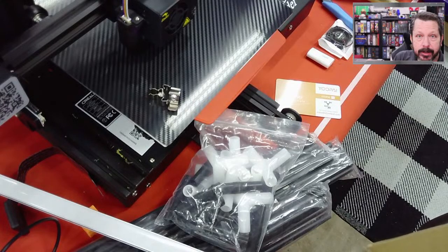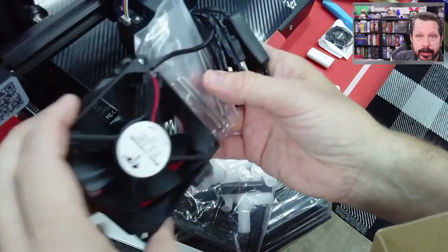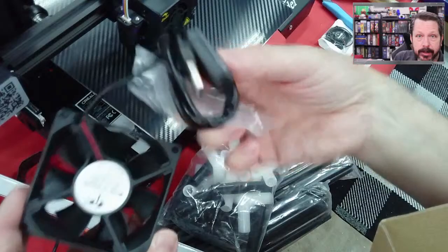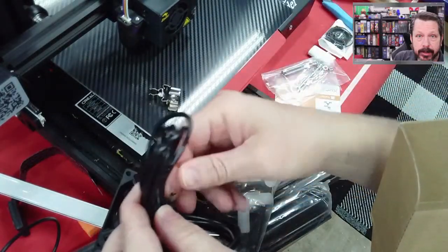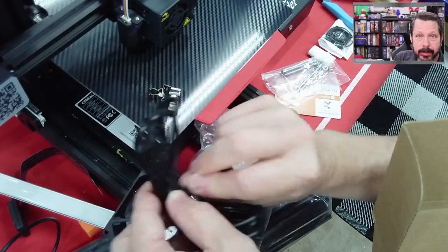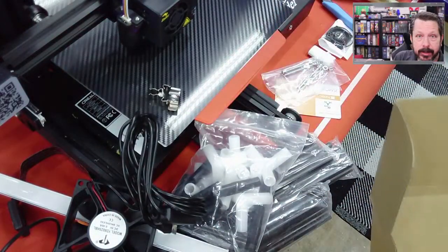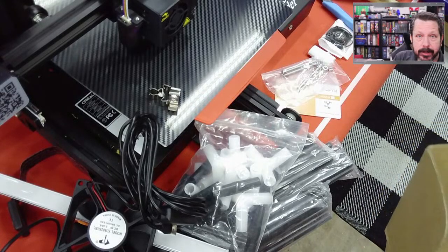Let's see. So PC DC brushless, another 0.4 amps, 5 volts. So that is also another one. Now, how many of these things can I run off of the Raspberry Pi at the same time? I don't know. You know, I've got a 2.5 amp power supply. The LEDs probably don't draw that many amps. This thing says it's going to draw 0.4, so I'm left with 2.1.